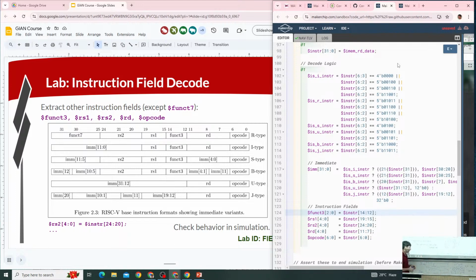When you're talking about the immediate, you can look at the instruction and say where those immediate bits are going to in the immediate field, or you can look at the immediate field and say where the immediate bits are coming from in the instruction. They're just inverse mappings of each other, right? You're mapping bits of the instruction to the bits of the immediate field, and you can represent the table either way, with respect to the immediate bits or with respect to the instruction bits.